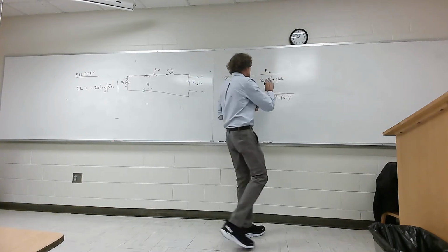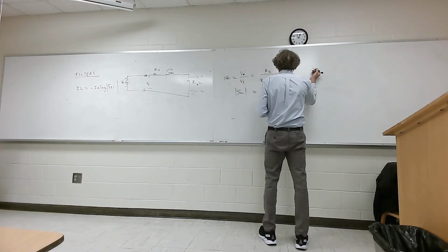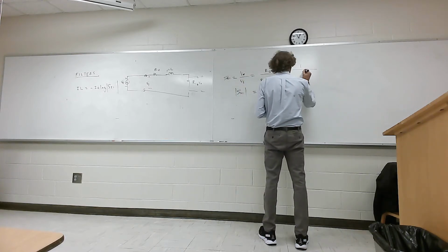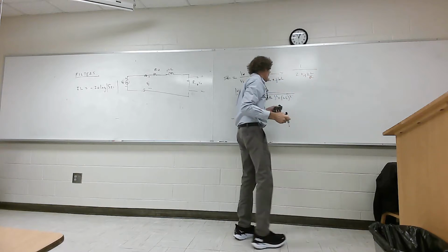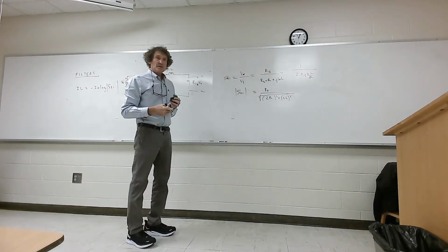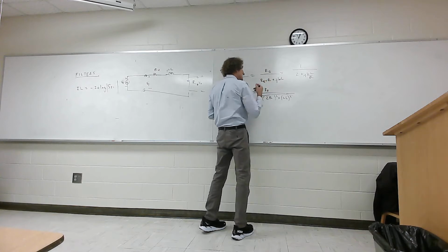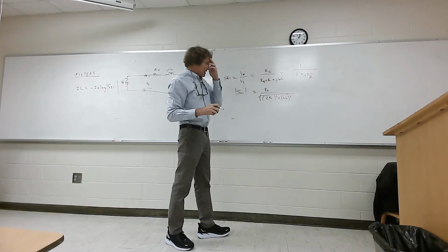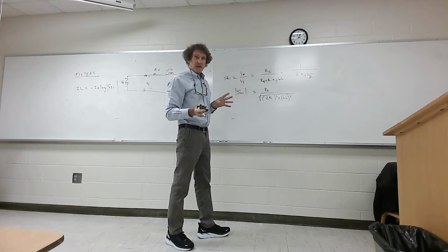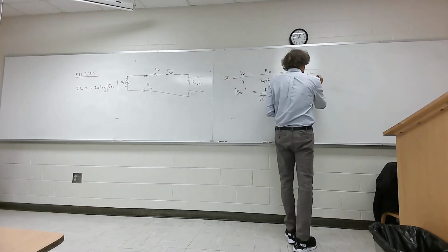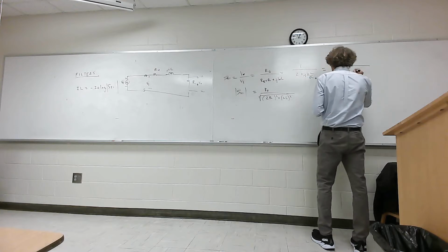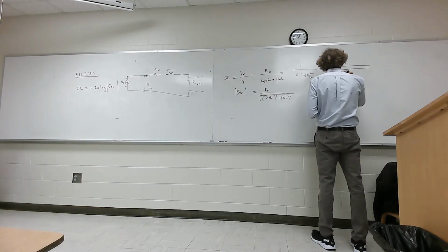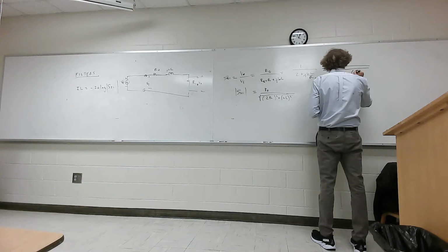Something else I'm going to mention here. If this is the case, we can simplify this, and we can just say that's 1 over 2 plus j omega L over R. Do y'all follow me? I'm dividing top and bottom by R naught, since this is in fact R naught, because he says R naught is RL. Do y'all follow me in this class? Okay. Now, if I take the magnitude, I have 1 over the square root of 4 plus omega L over R, squared.